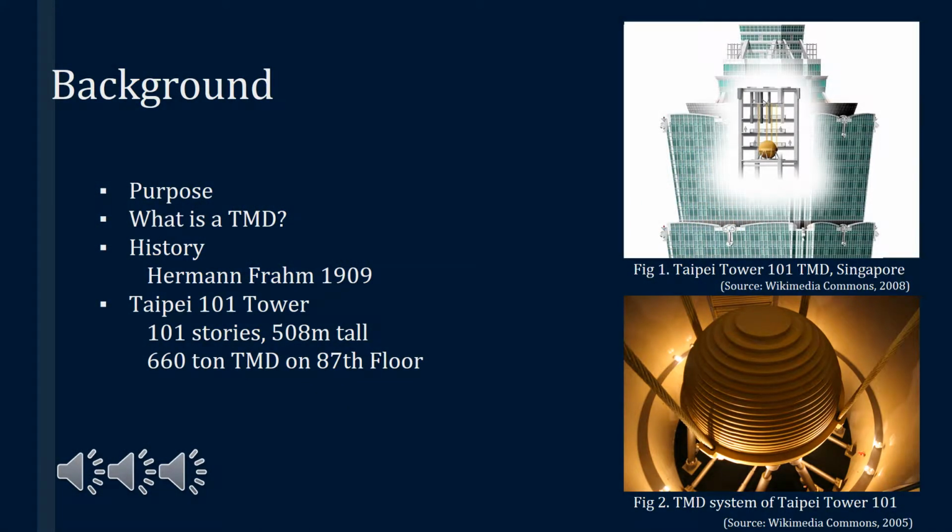When a structure is subjected to an earthquake or to the action of strong winds, a certain amount of energy is introduced into the structure. For moderate to strong earthquake or wind excitations, a substantial amount of the total energy introduced in the structure is dissipated as hysteretic energy. Physically, it represents energy dissipated through nonlinear behavior of the structural members after yielding, and the more hysteretic energy dissipated, the higher the structural damage.